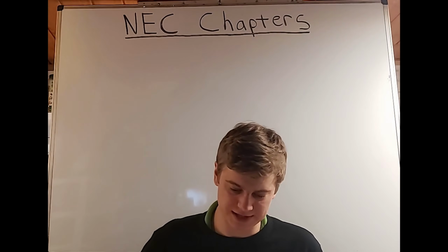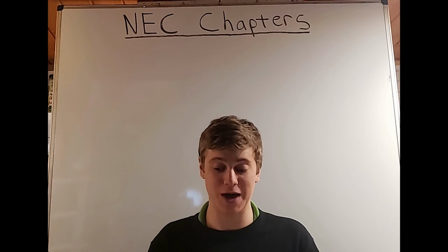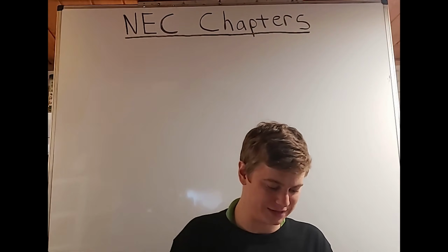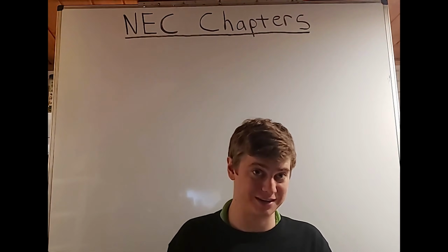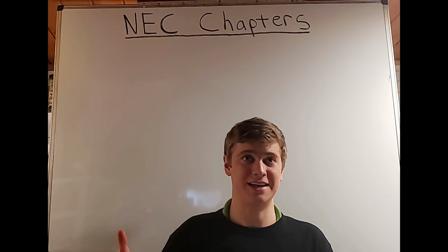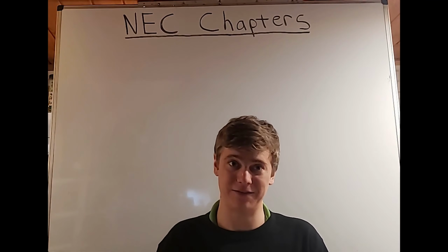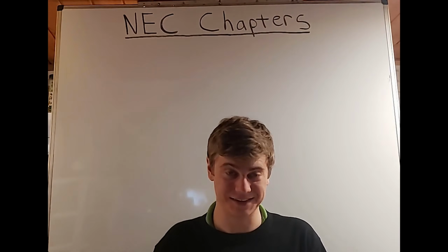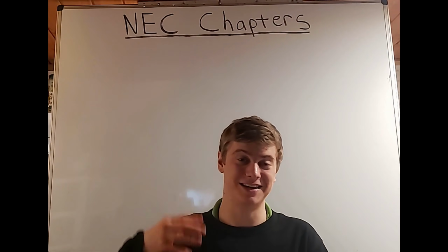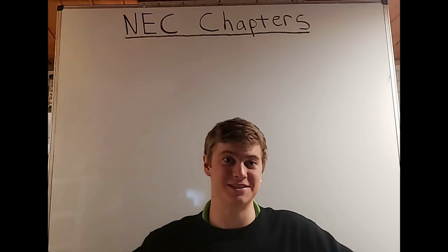Okay, we have table 310.16, the ampacities of insulated conductors with not more than 3 current carrying conductors. So that's why you have the table for the more than 3 current carrying conductors I mentioned right before this. This is kind of funny because if you know from the NEC 2017, then this was called table 310.15(B)(16). Okay, instead of all that madness, now they just turned it into table 310.16, which is actually what it was before NEC 2017. Kind of crazy.